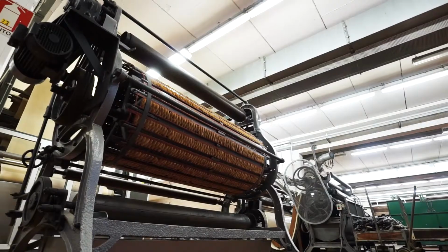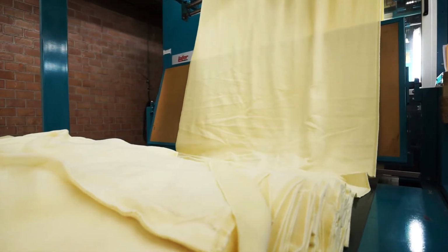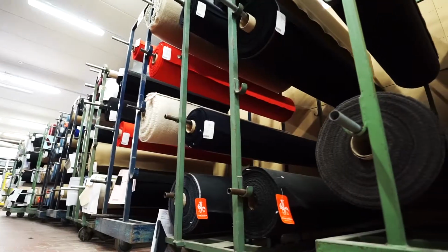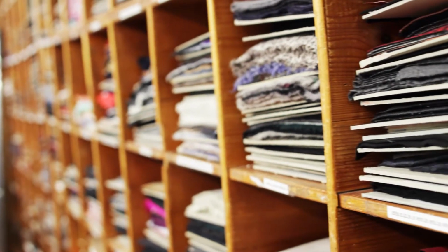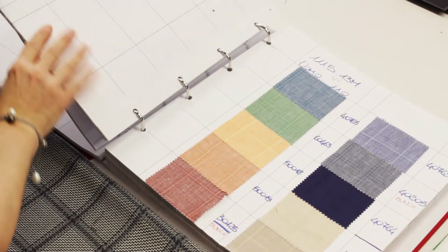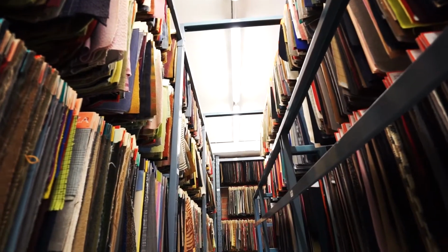It is the process part where the fibers are taken out from the surface of the fabric. The raising gives the characteristics the finishing has, the surface characteristics and the touch. After the raising, there is the final part of the dry finishing and the quality control. To give an idea, we have per each collection about 200 or more fabrics, each one with all its color proposals, which can reach about 40 colors for some fabrics.